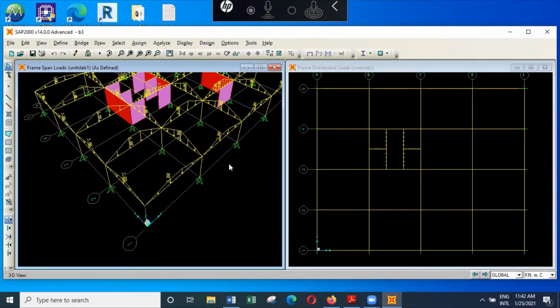But when you have secondary beams, the only disadvantage is that, certainly you will need less reinforcement because the spans are lower, but you will have the problem of casting additional secondary beams, which can be a little more labor intensive, and also fixing reinforcement may have some little difficulties. But other than that, it's possible to use secondary beams if you like. But in this particular example, I have not used any secondary beams.